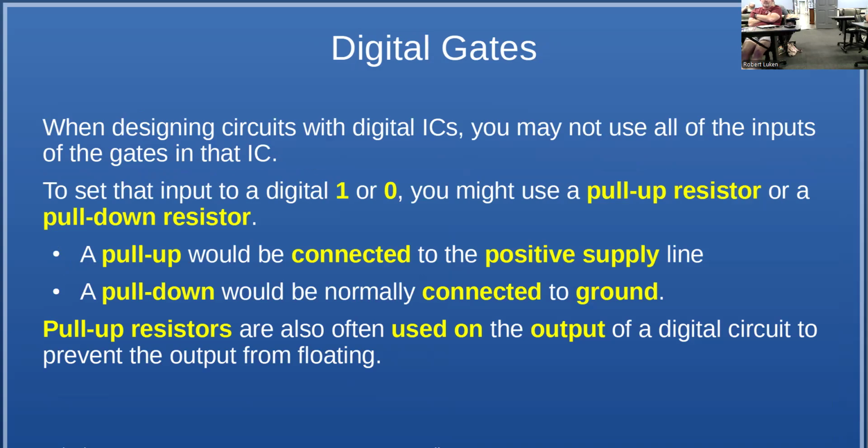If it's just floating, noise can cause it to switch back and forth, which can generate a lot of noise in the system. In the case of CMOS devices, they can get biased in the middle, in the linear region, so it's on all the time, and heat up. And because the junction heats, resistance goes down, creating more current, and they can go into thermal runaway.